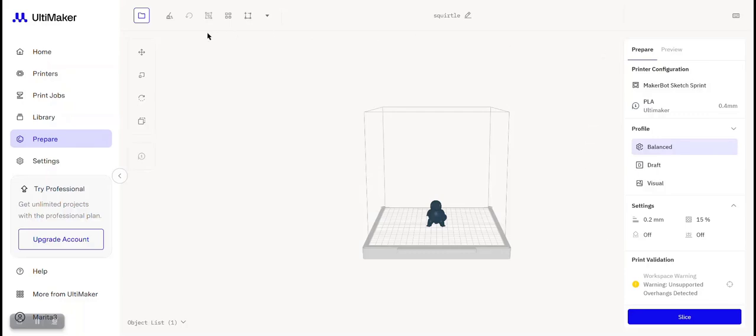Now let's dive more in depth on the left menu. If I select the first option, you'll see that the workspace uses a coordinate system. You can specify the amount of units you want to move an object in a specific direction. To center your objects, you can set the values to 0. You can also manually move the model by selecting and dragging the red, green, and blue arrows. These arrows correspond to the X, Y, and Z axes.